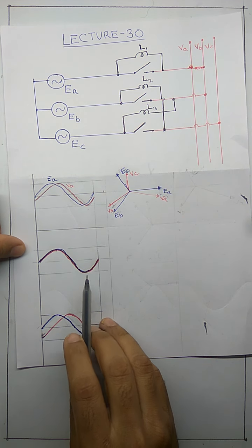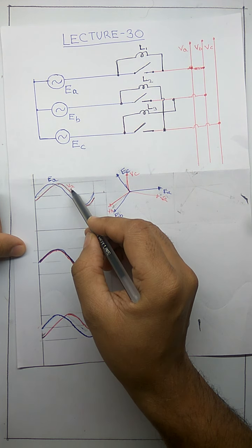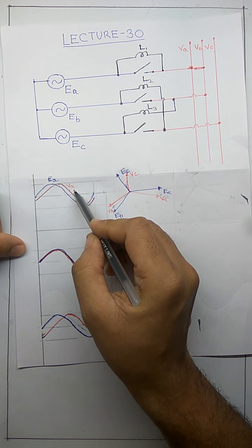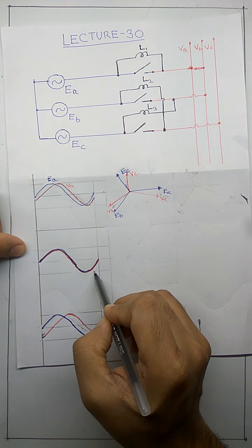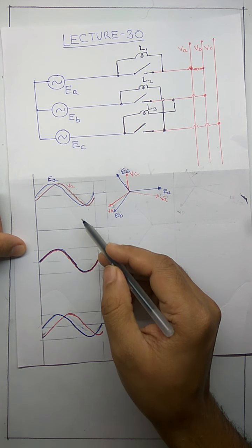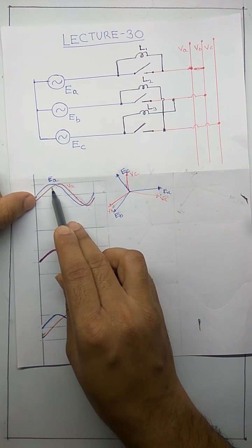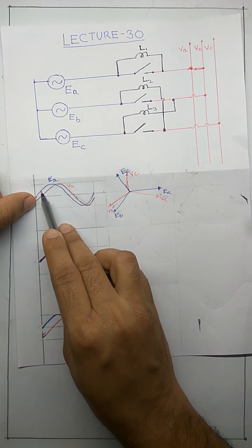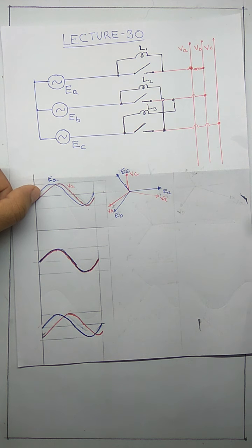This is shown here. So here the incoming generator is leading the grid voltage, and if after some time it comes to this position, it means that my incoming generator is slower. That's why this has lagged to this. That is, previously this was lagging, after some time it has come in phase, so this is slower. What will be the phasor diagram in this condition?